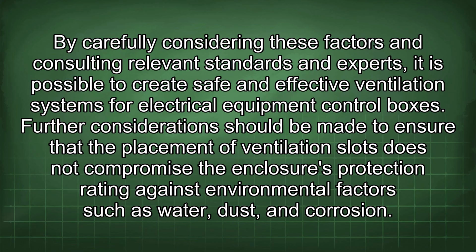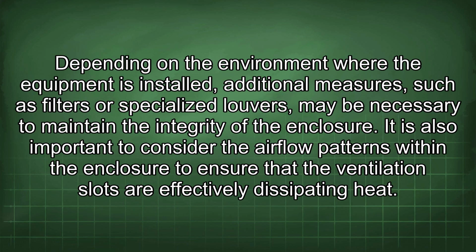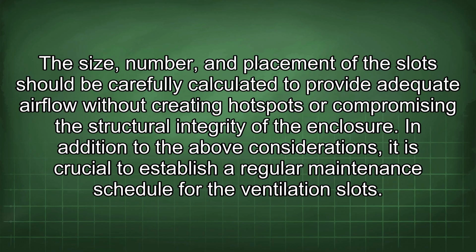Further consideration should be made to ensure that the placement of ventilation slots does not compromise the enclosure's protection rating against environmental factors such as water, dust, and corrosion. Depending on the environment where the equipment is installed, additional measures such as filters or specialized louvers may be necessary to maintain the integrity of the enclosure. It is also important to consider the airflow patterns within the enclosure to ensure that the ventilation slots are effectively dissipating heat. The size, number, and placement of the slots should be carefully calculated to provide adequate airflow without creating hotspots or compromising the structural integrity of the enclosure.